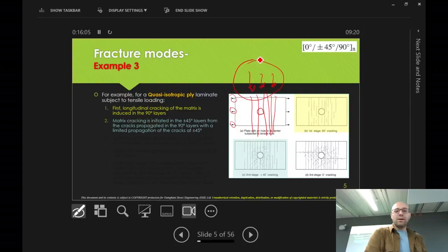You don't want that. And also, bearing in mind these kinds of stacking sequences, I'm probably not going to tell you, or maybe I will tell you later, there are some rules about stacking, particularly for aerospace. How much of each ply you need to use. For example, one of the rules is a 10% rule. Even if the loading doesn't require it, you must have a minimum of 10% of the plies in all directions. 10% in 90 degrees, 10% in 45 degrees.